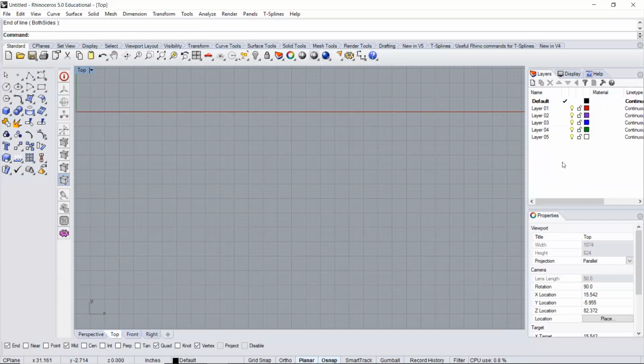The main thing we want to be able to do is toggle into the layers and into the properties. And so on a Mac, you probably have a series of icons across both, and you can use the first 2 of those icons in order to get both of these. And if you don't see this at all, it may be because you've got a sidebar option right here that needs to be checked on. Within our layers, if you've worked with layers in Illustrator or Photoshop, they're really similar to how they operate in Rhino.